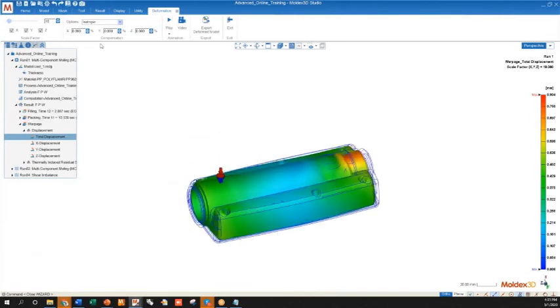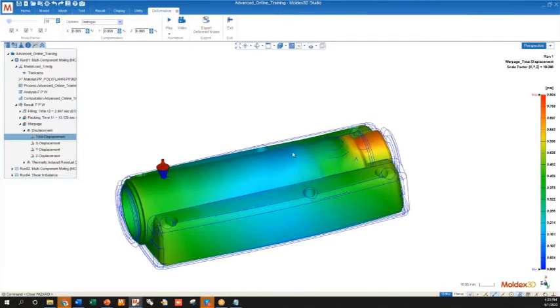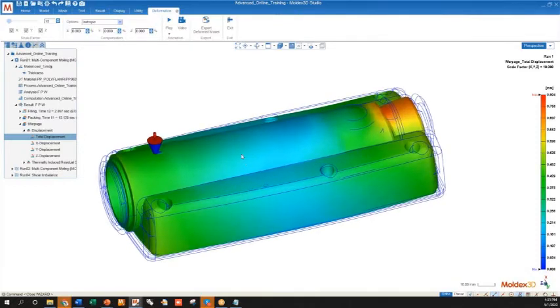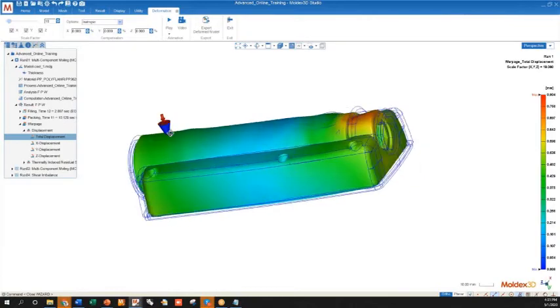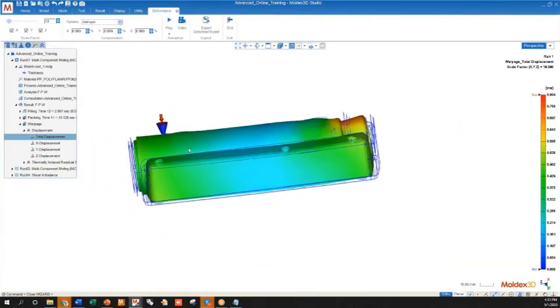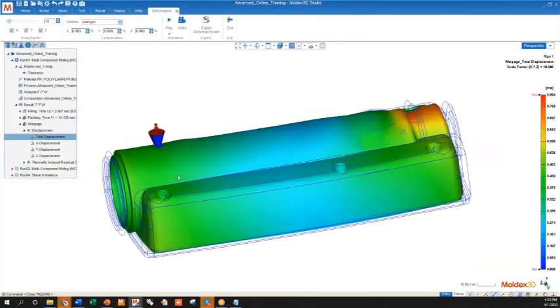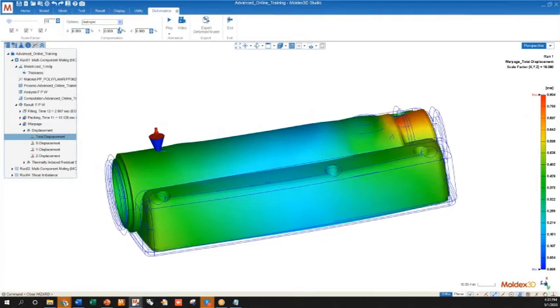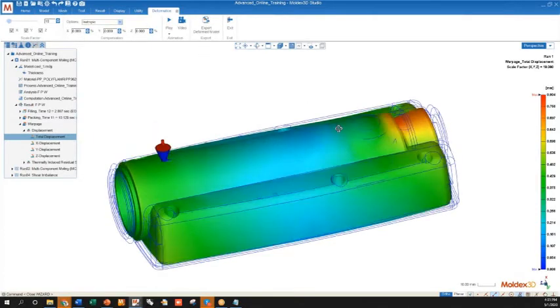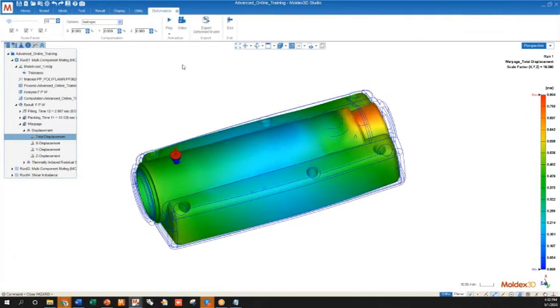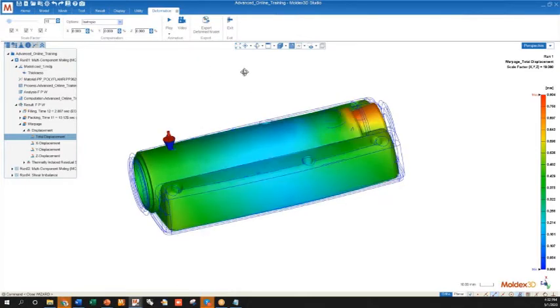We do that through the compensation tool, and with the compensation tool, you can either use the material shrinkage value or you can use Moldex3D's value. I'm going to go through the more complicated approach and use the Moldex3D value, but you can also use an isotropic material shrinkage value as well. Those are usually pretty close to one another. To obtain what we call anisotropic compensation percentages, we're going to go to the Warpage Log file.